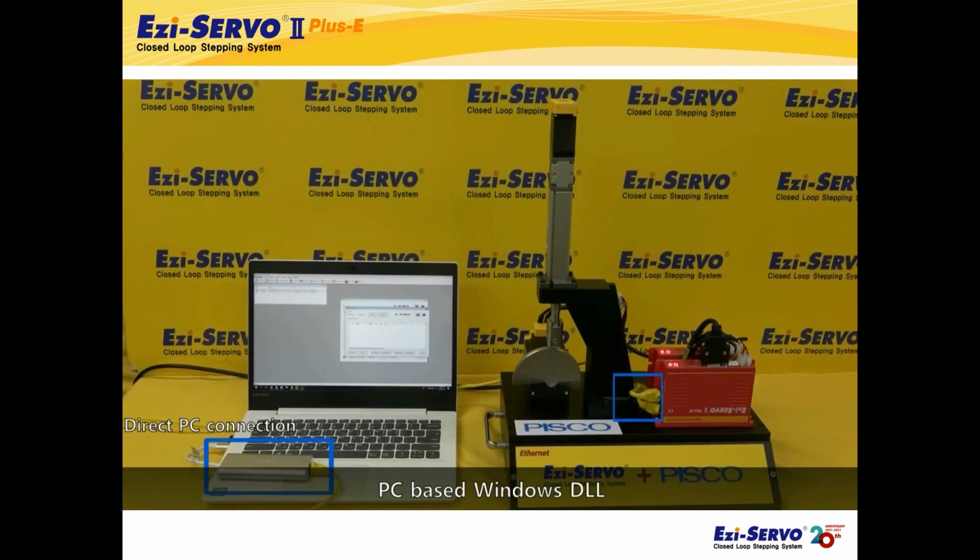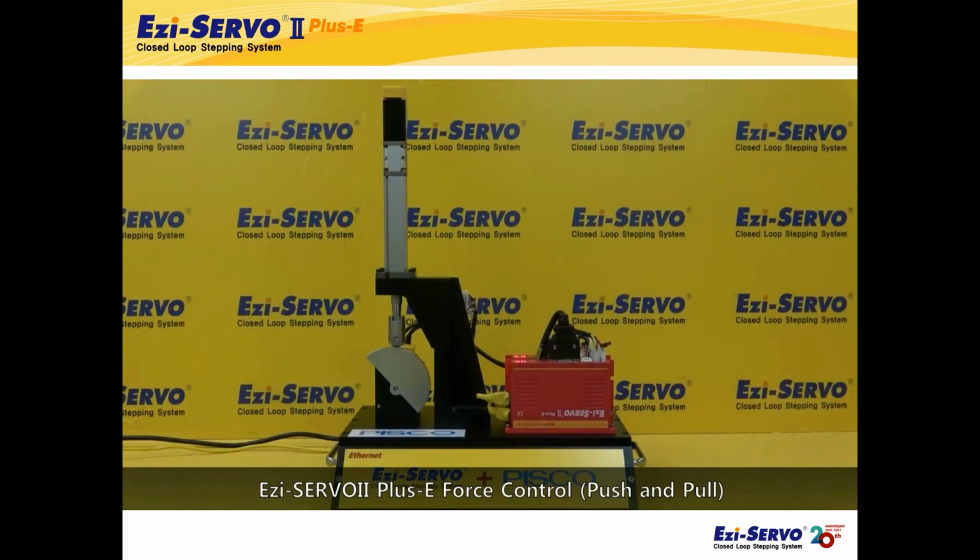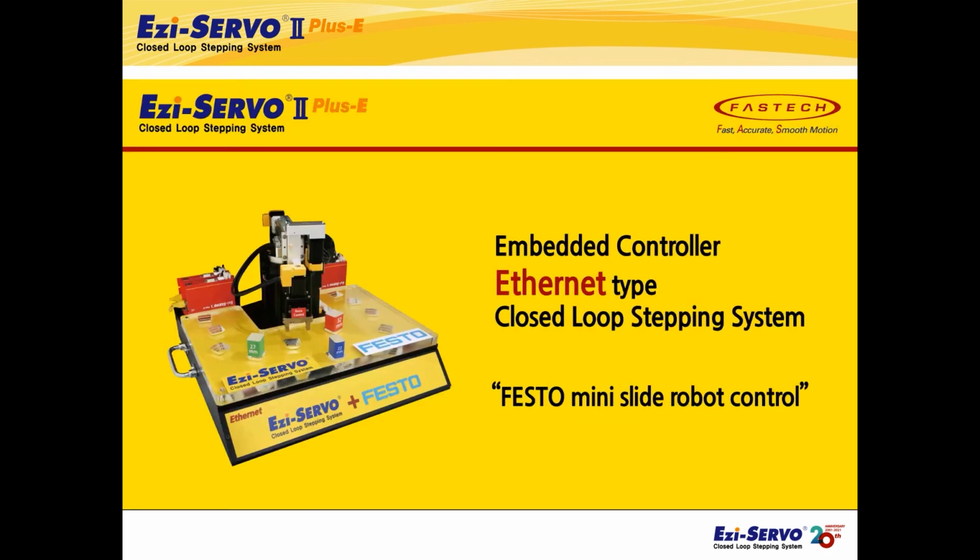This is a necessary control method when the target position value varies depending on the object, for example, when picking up objects of different sizes with a gripper, or when fastening objects with different heights. Lastly, let's look at another demonstration that shows force control.